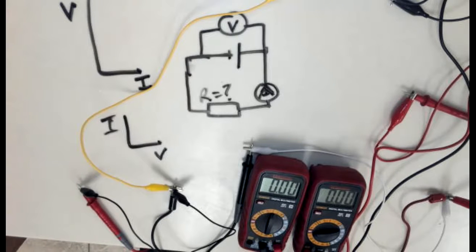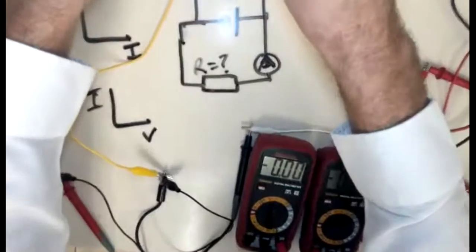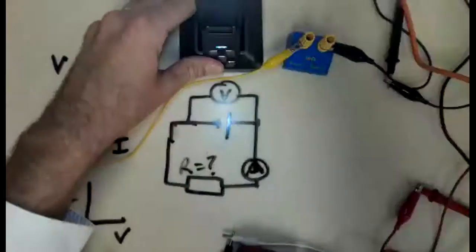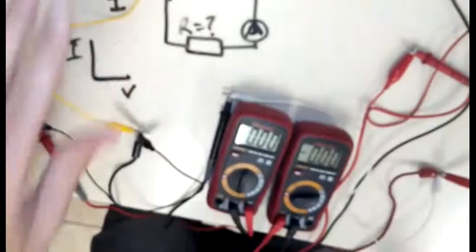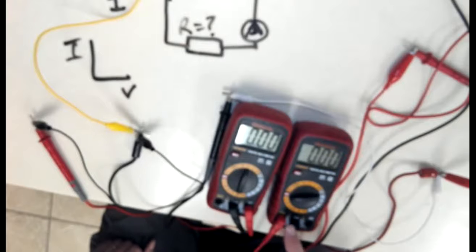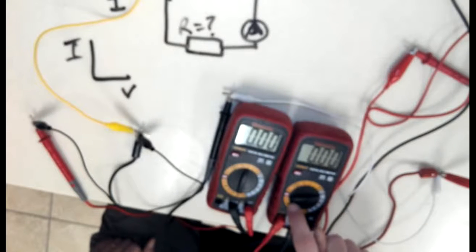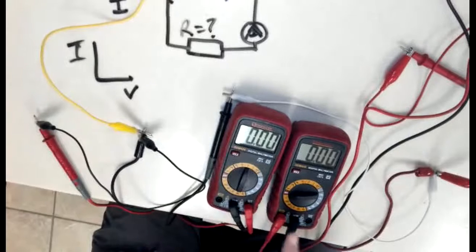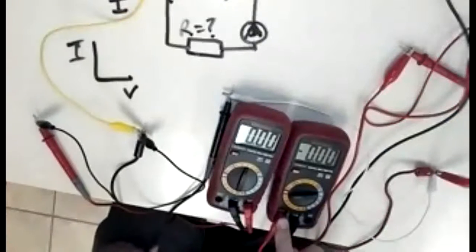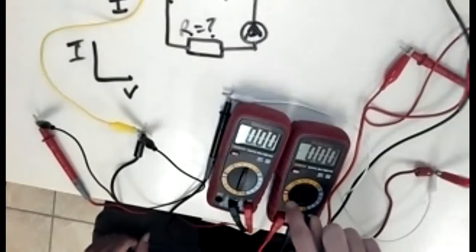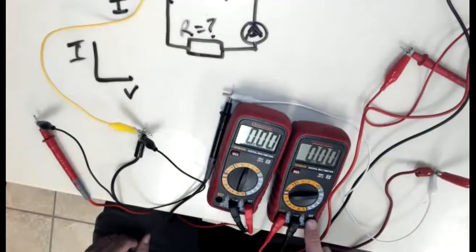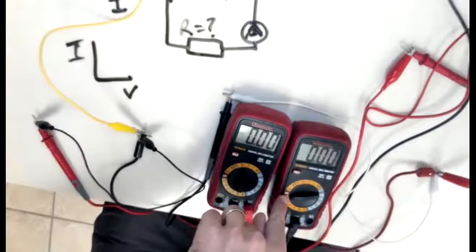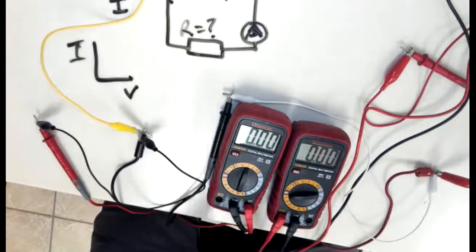All right, and see, the thing about the multimeters here. This multimeter, the ammeter, it's set to the 10 amp range because the next lowest range measures up to 200 milliamps. And you actually need to disconnect the red lead here; it's in a special 10 amp port. It's high current, so there's a special setting for that where you literally have to unplug it and plug it in here. We'll quickly exceed the range of 200 milliamps with the voltages that we can achieve here, and then this thing will say OL, overload. And so rather than unplugging it and plugging it back in, I said, well, we'll just measure everything on the 10 amp range, and we won't overload it hopefully, but we would have to change it. And time permitting, maybe we'll see that.